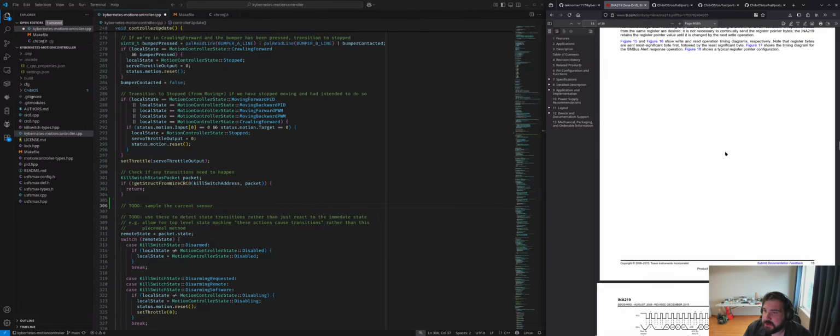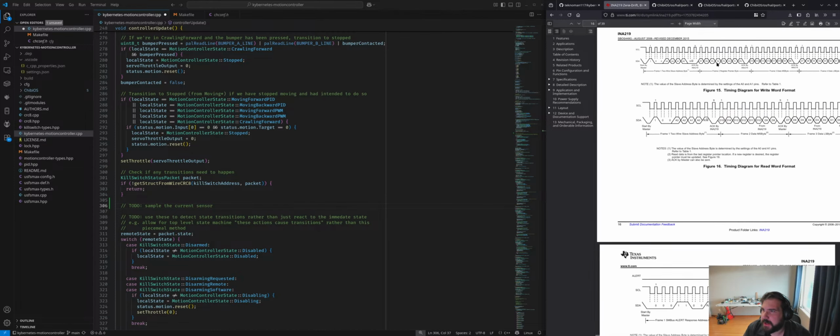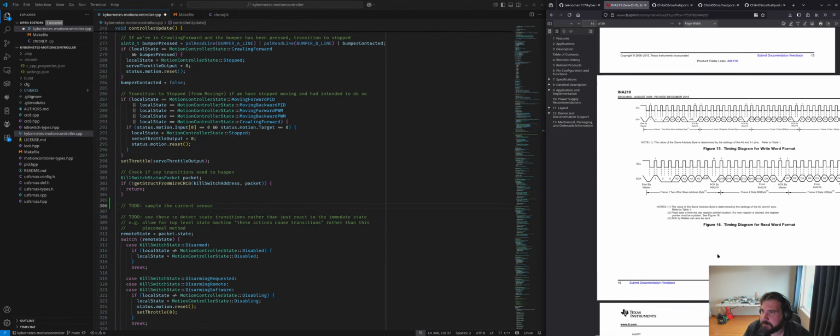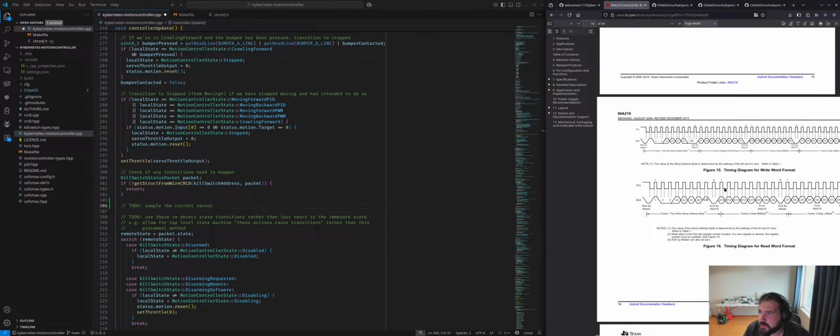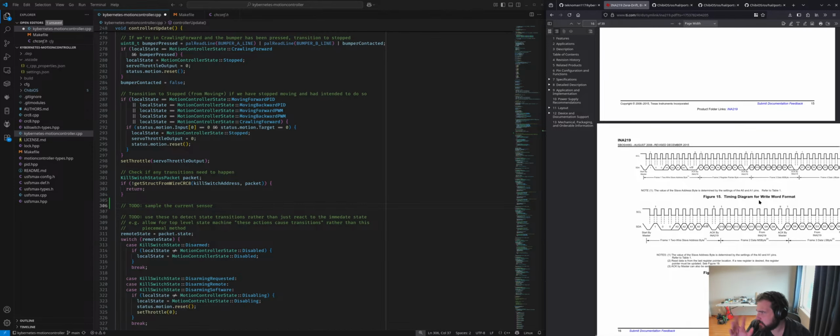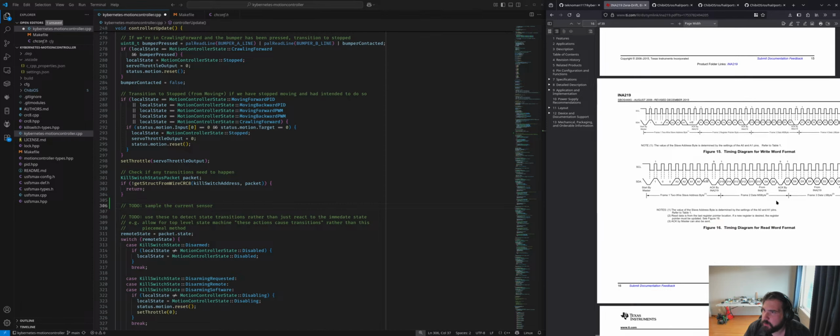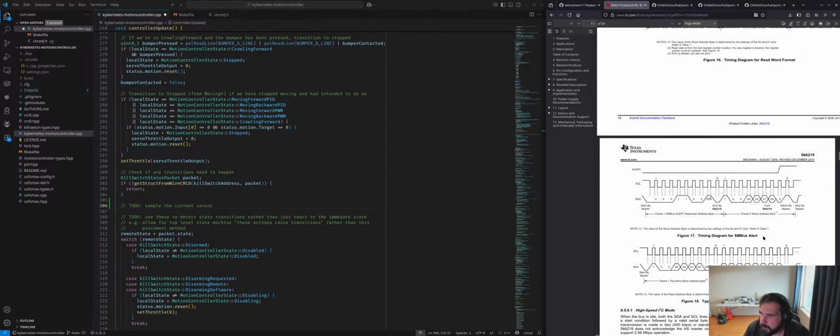Let's start with figuring out the framing. I2C is I2C, but sometimes you can do 8-bit frames, and sometimes you can do 16-bit frames. The INA uses the word format. Here's the timing diagram for SMBus alert.